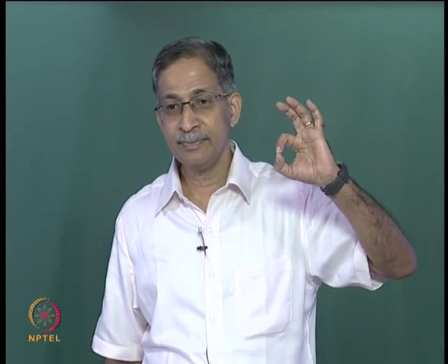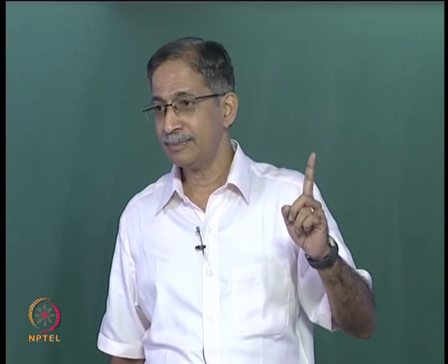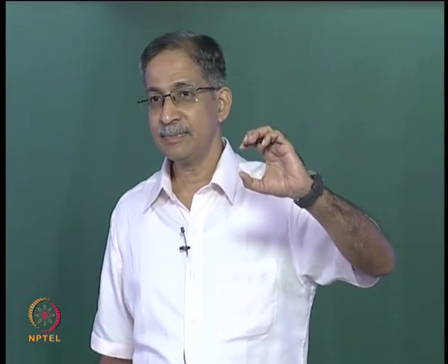Why is it not good? It belongs to KAA. KAA becomes singular, you can't invert it, you can't find a solution. So what do you do? So that is a problem. You have a diagonal element in your structure stiffness matrix because of the moment release which has 0. So what do you do?